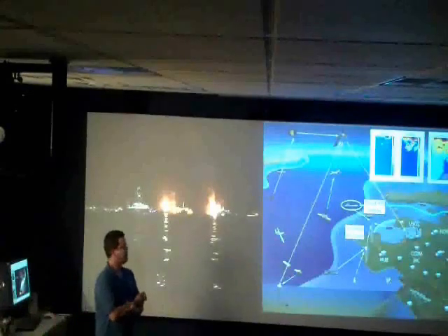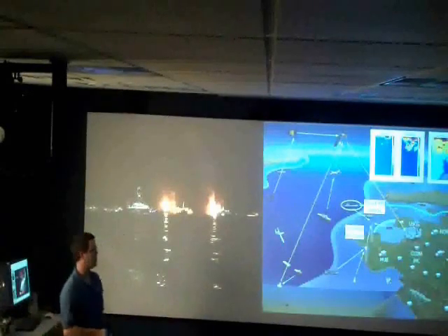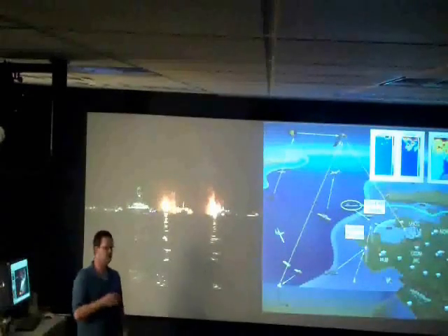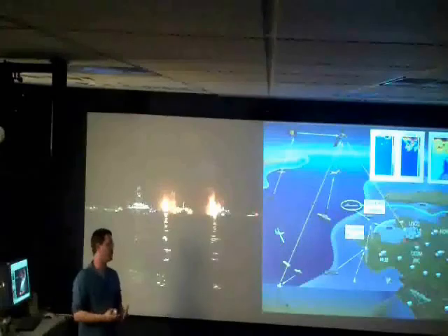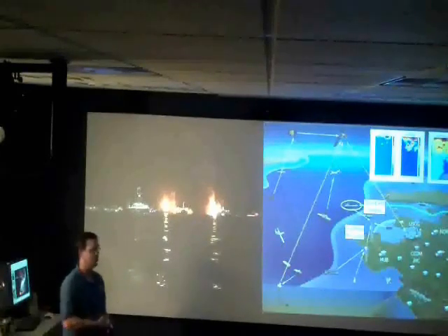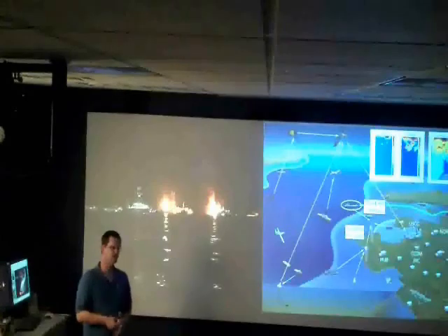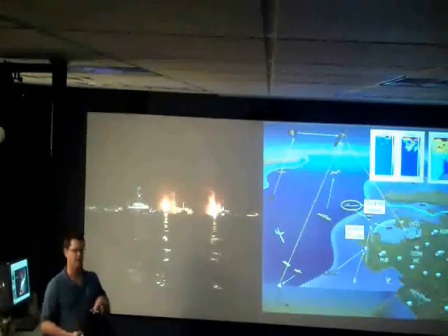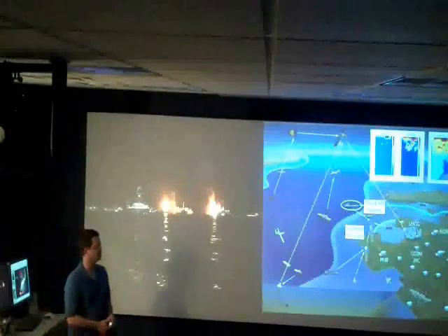And the idea then is you can build a system that's going to watch the environment and do risk analysis. So here's some figures from Brian Calder that look at this and look at the risk of grounding and having a ship incident where you have to have a response sent out. And then you can try to mitigate that. You can tell a ship, I'm sorry, you can't come in at this tidal regime because there's just not enough water between you and the bottom for our particular harbor.